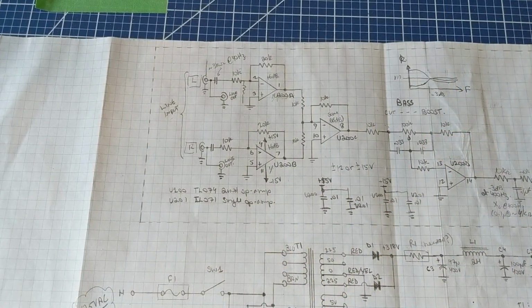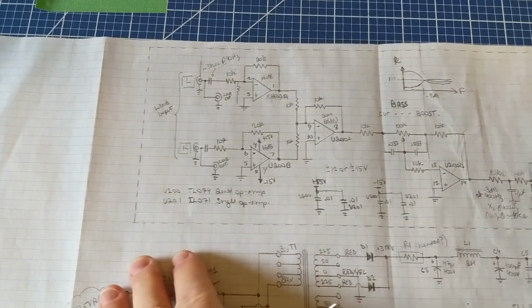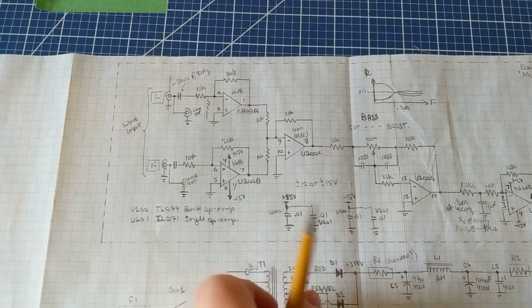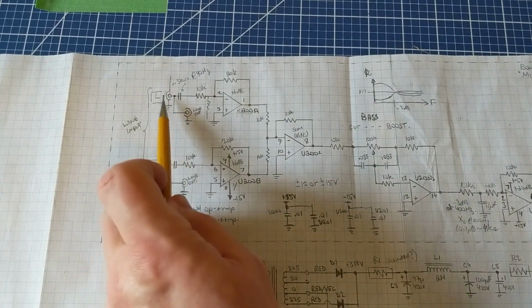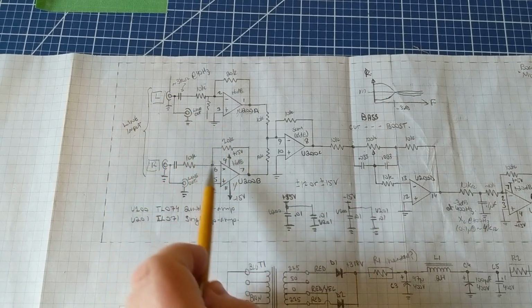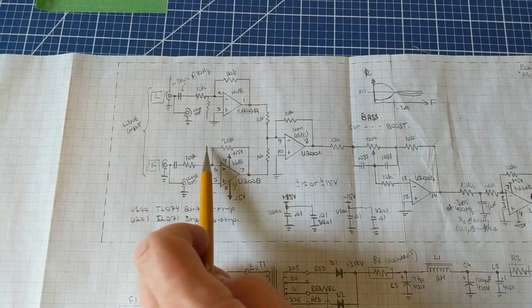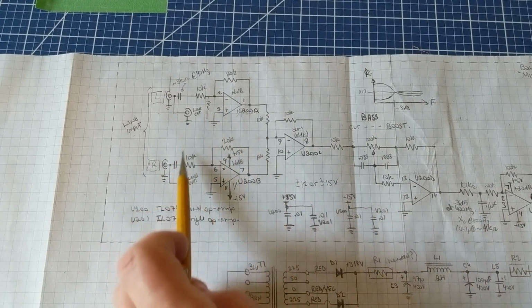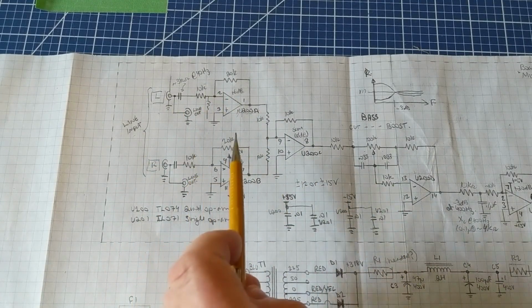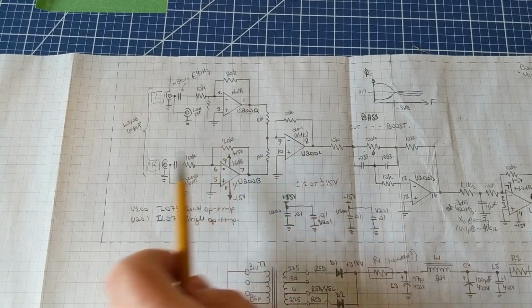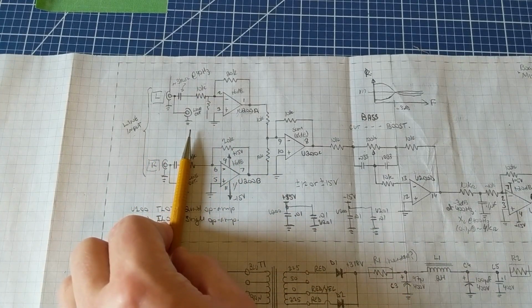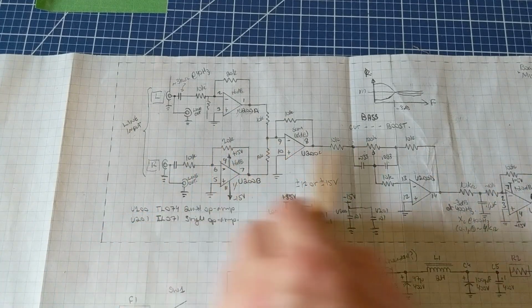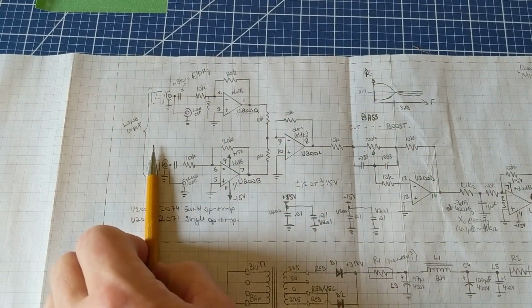This is the sketch I made for the main circuit. Right here we see the input section, the preamp, which has the left and right audio input as well as the pass-through. Missing in the schematic is something I have to add in. I moved the volume control to the front here to allow me to just set the voltage input right at the beginning so that nothing saturates down the line if the line voltage is too high.